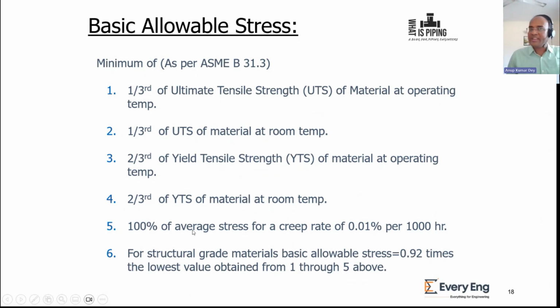There are two or three more criteria. So based on that, whatever values we are getting, we have to calculate and find the minimum. Whatever is minimum, that will be known as the basic allowable stress.